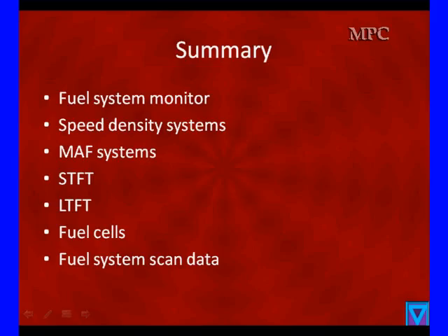Very few cars have fuel pressure. If you don't have fuel pressure, you have no idea if fuel pressure is good or bad on the vehicle. You have no idea if fuel delivery is sufficient. And remember, fuel delivery at idle is not the same as fuel delivery when the vehicle is operating under driving conditions. Drive the vehicle where it failed as indicated by freeze frame.